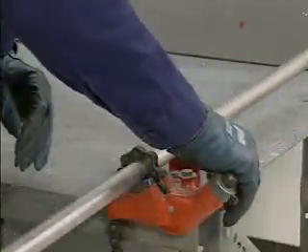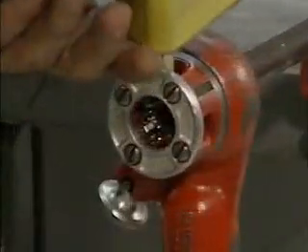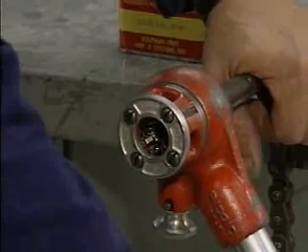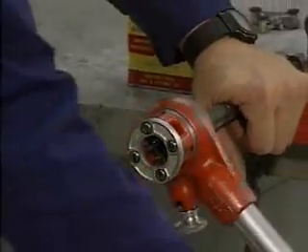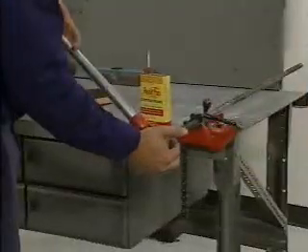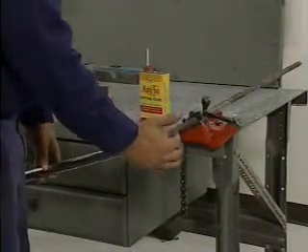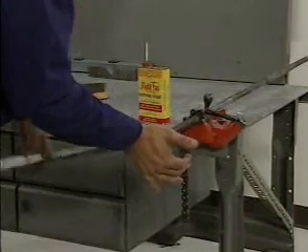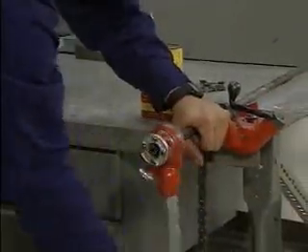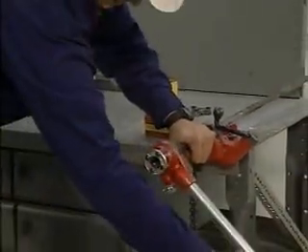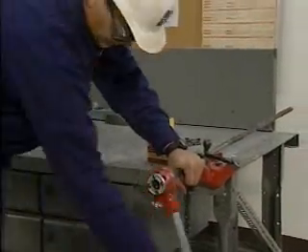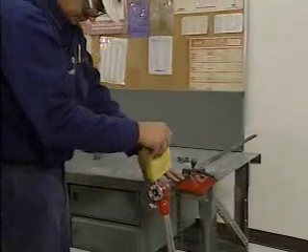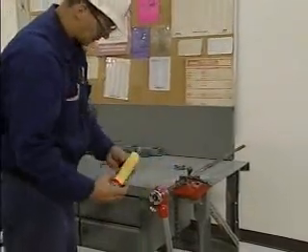There are a few basic steps to hand threading a pipe with a pipe die. First, you should secure the pipe in a pipe vise and apply cutting oil to the end of the pipe. This provides lubrication and reduces the heat that's generated when the die cuts into the pipe. Next, press the die against the end of the pipe and turn it clockwise with a ratchet handle. Once the teeth of the die grab the pipe, you can continue turning the die without having to press it against the pipe. It may be necessary to apply additional cutting oil after a few turns as well.